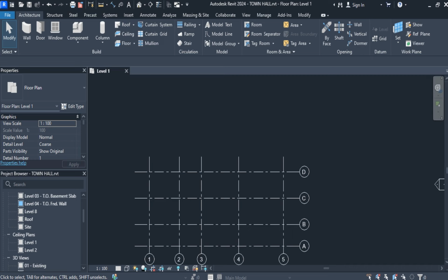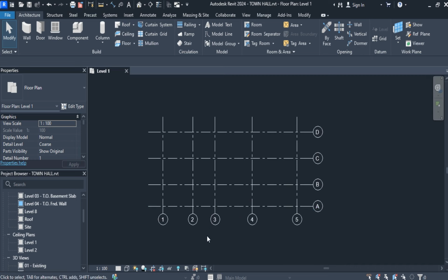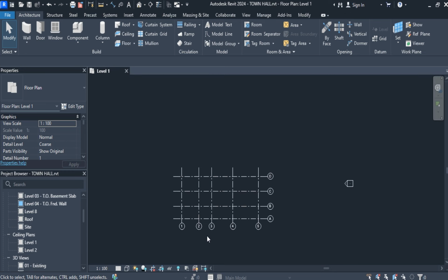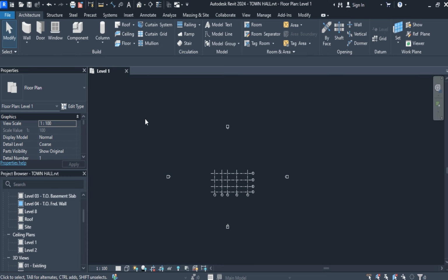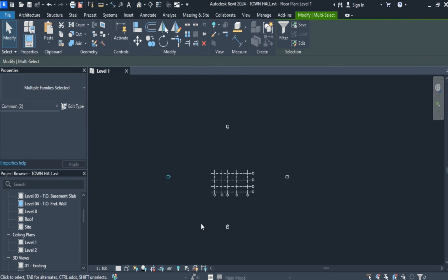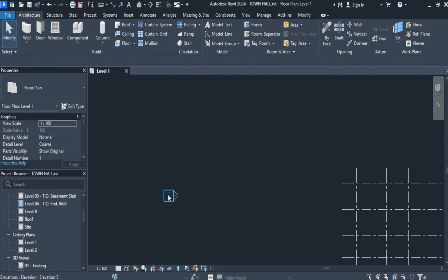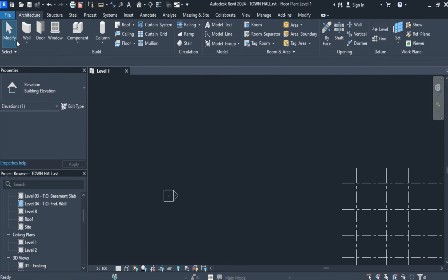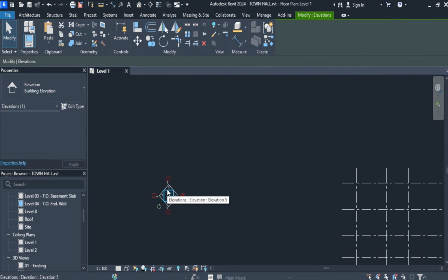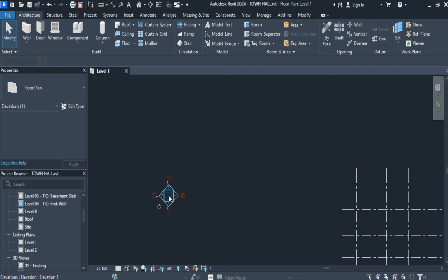So next we shall go to creating levels, and to create levels we need to be in elevations. The shortcut for creating levels is LL, or the level tool is here. When you open your template, you'll have the default levels. This one. When you double click on the level head, straight double click on the level, it should open to where it should be showing.